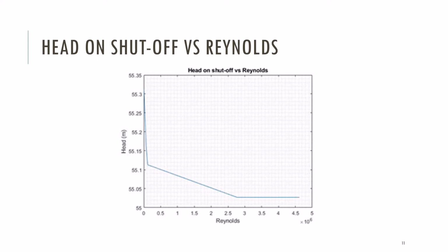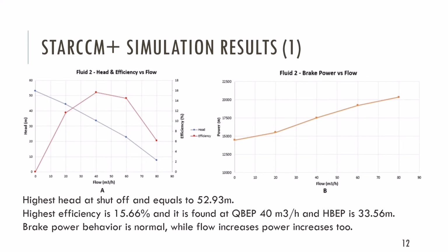In this case, for each fluid, different factors could affect the relationship between the two values shown above. For example, viscous liquids require more energy at the best efficiency point. As energy increases, head also increases. On the other hand, Reynolds number changes with physical properties such as viscosity and density. As viscosity increases, Reynolds number decreases, and in parallel, as density increases, Reynolds number decreases its value.